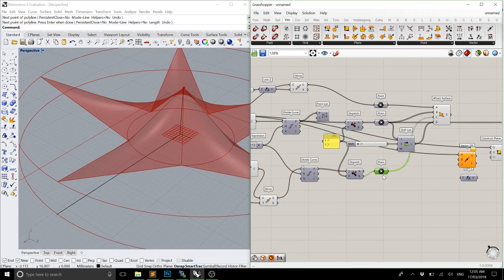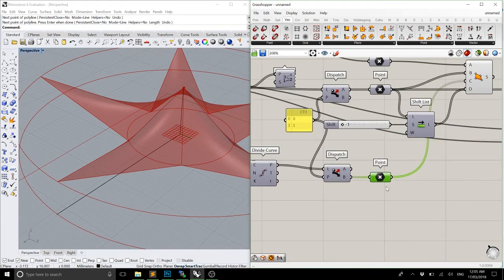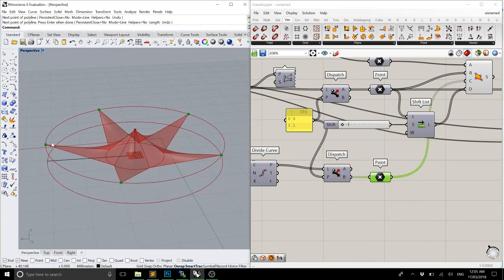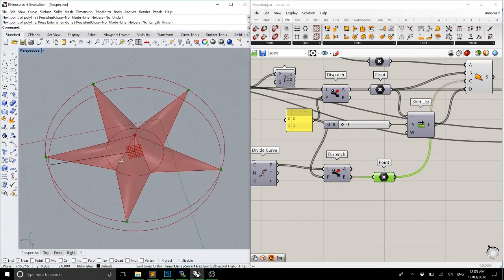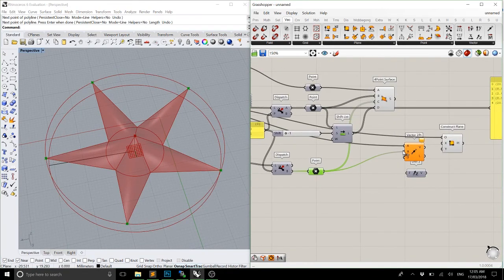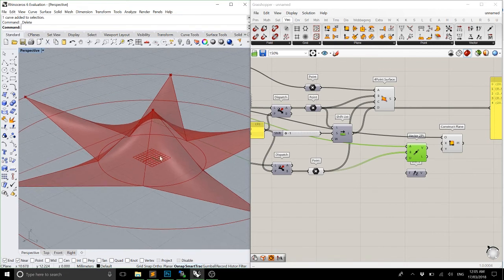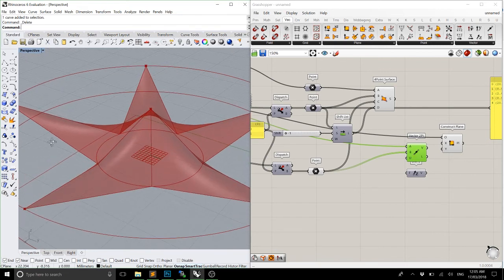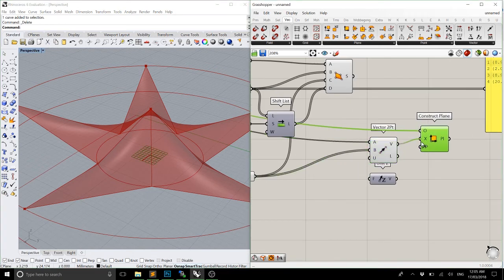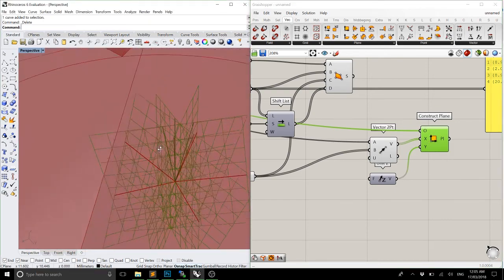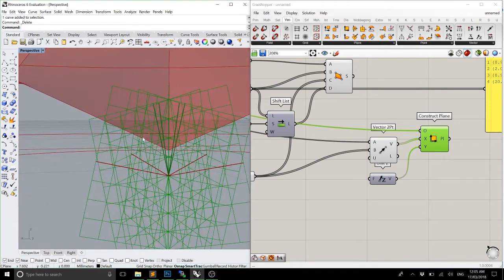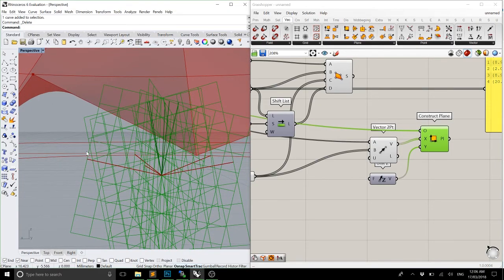The outer edges, and just if you tap into your short-term memory, that's these guys. We can preview them just to make sure. So these guys are the outer edges of our geometry. They go into the B section, so that's now creating a vector. Vectors aren't actually visible geometry, otherwise they would be called lines. There are ways of previewing them, but I'm very confident these are doing what we need them to do. So these go into the X parameter of our plane, and then Z goes into the Y, and we can see Grasshopper displays a little square with a grid in it.